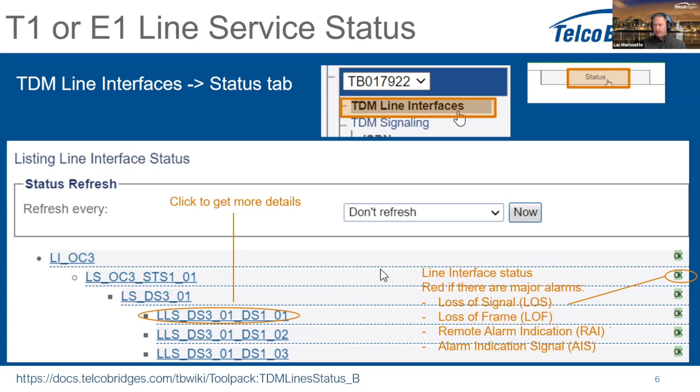The remote alarm indication here is the remote side telling you that you are not sending the information. Okay, so RAI is still interesting to see because you know that you are connected somewhere, and the other side tells you that he's not receiving the data you're sending him. So you need to check maybe the physical line to see if it's being transmitted correctly. But there's also some tests that can be done, and we'll use the RAI alarm. And I will show you on the next page.